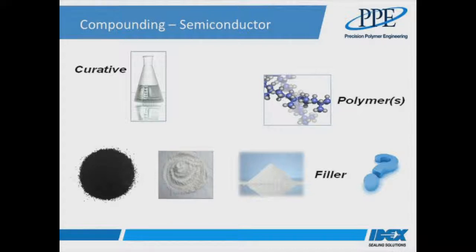The disadvantage is for some semiconductor applications, and as we've already alluded to, the breakdown in the higher elastomer structure results in transferable residues or particles which are undesirable, especially where the seal is in one of those critical locations in a process tool. The carbon black manufacturing process has been around a long time and is also less stringent, and impurities or contaminants are more uncontrolled. The requirements of the semiconductor industry were just not taken into account in carbon black manufacture.